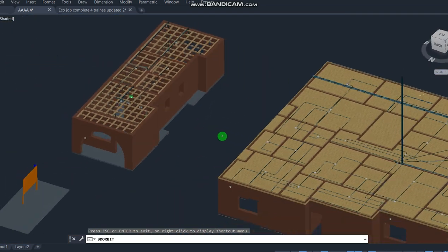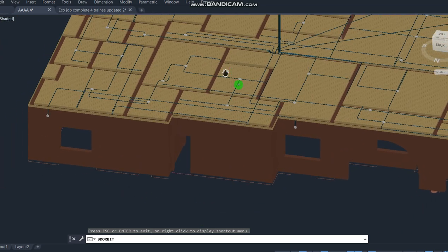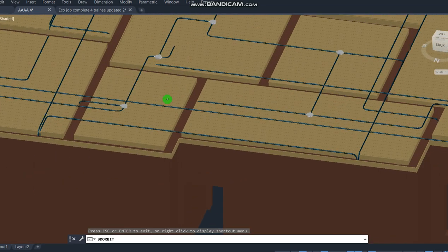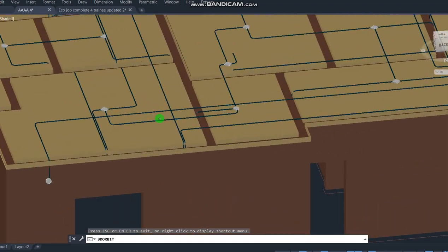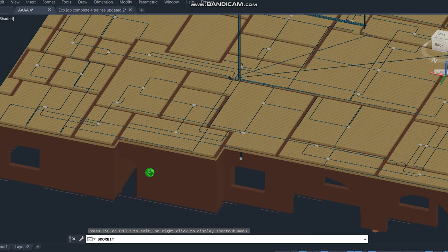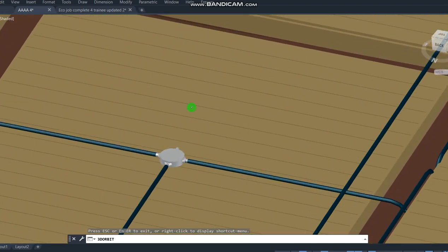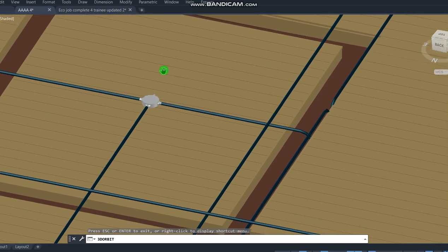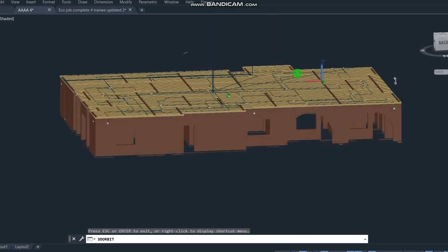After the piping, you also do your piping calculation, your installation calculation, how to identify the number of sockets and the number of circuits required in a particular building. So we teach you all that. For the decking, we teach you how to bury your knockout boxes and how to do your piping stage. After that, there's going to be a decking. Civil work will take place after your work. After the civil work, you continue to the next, first floor.